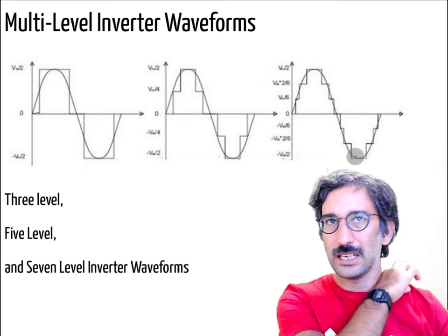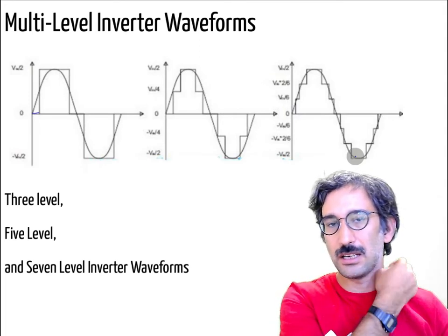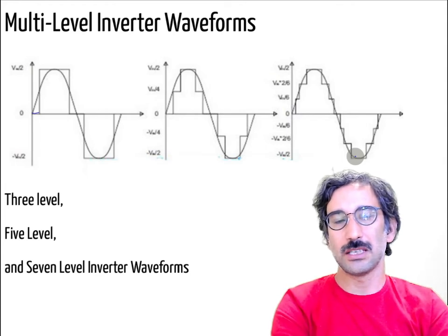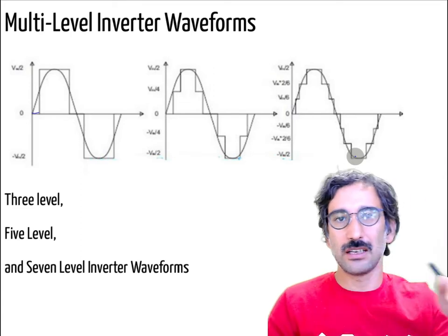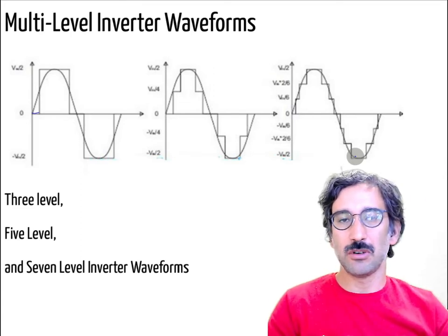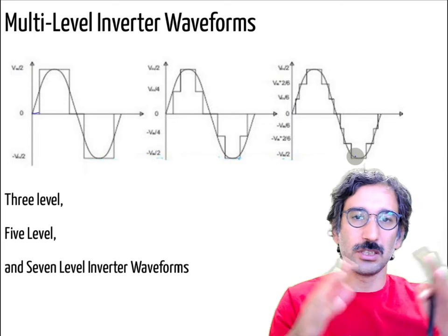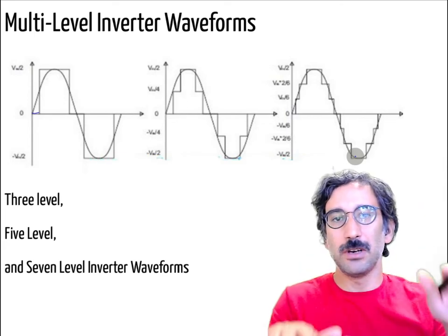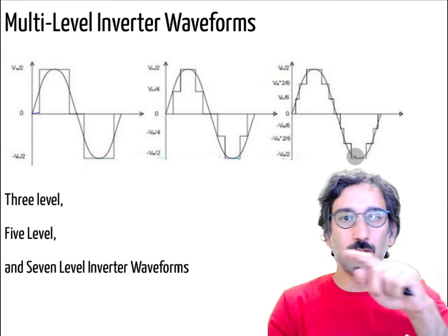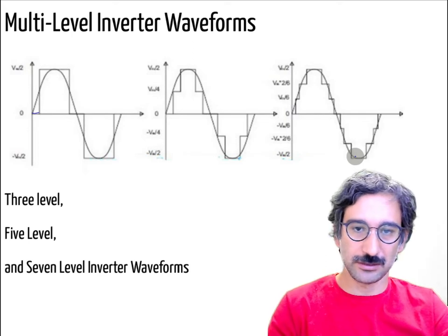An analogy of that thing we actually use in electrical machines, as you've seen last semester. Instead of using concentrated windings which generate kind of square MMF waveforms, I can use distributed windings. Remember A1, A2, A3, short pitches, that kind of things. The idea is to put those square waves on top of each other to get a more stepped waveform that can simulate a sinusoid better.